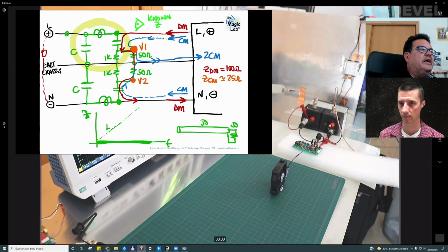Other line impedance stabilization networks introduce several switches. So with a switch in the front panel, you can configure, I want to measure line, I want to measure neutral. And the cables route the signals to the appropriate connectors.